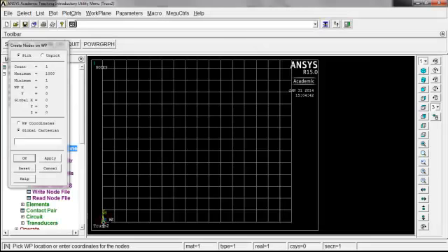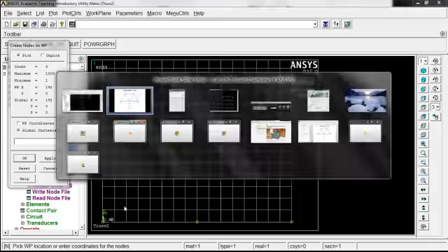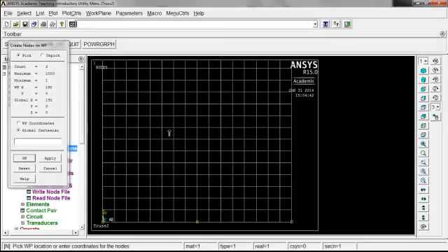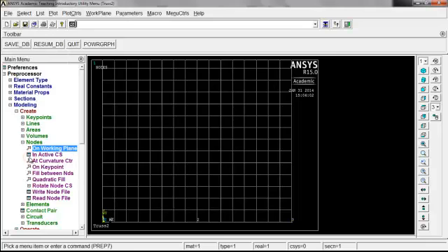So we'll go 1 is here, then 1, 2, 3, 4, 5, 6, 7, 8. There's going to be node 2. All right, we can see the number here as it's counting up. So 8, 1, 2, 3, oh, no, it's all the way over here, right? Because that's how we set it up, the 8 feet. Now as we go up, oh, it's not exactly on the foot, because well, it's 8 feet the length of the equilateral, so this is 8 feet here. But this right here, this dimension, we don't know for sure what that is. Well, I have an idea, a little bit less than 8 feet, but it's not right on the foot. So coming back here, we'll go ahead and click OK for those nodes, so apply those ones.